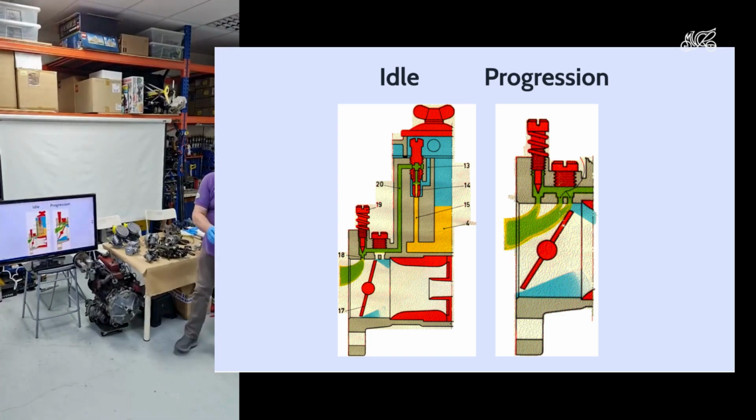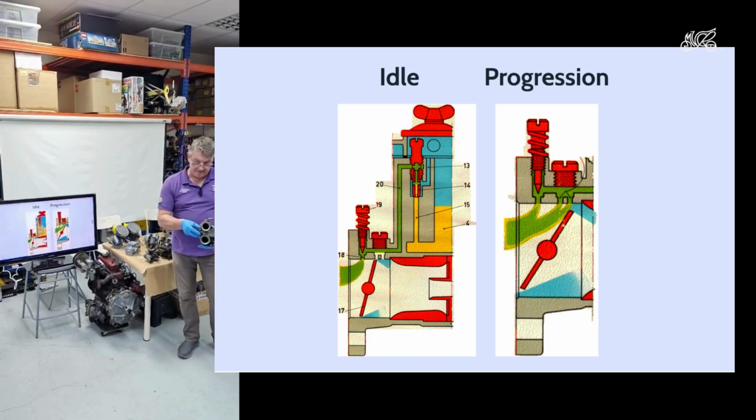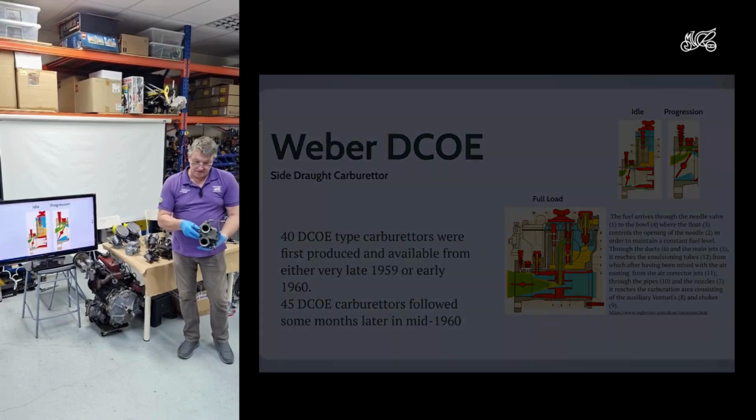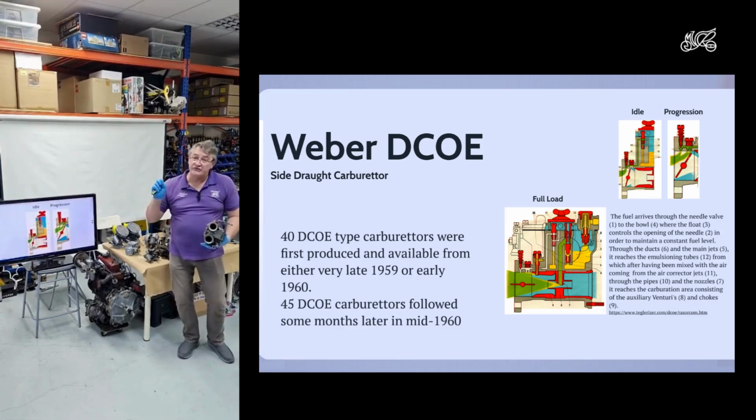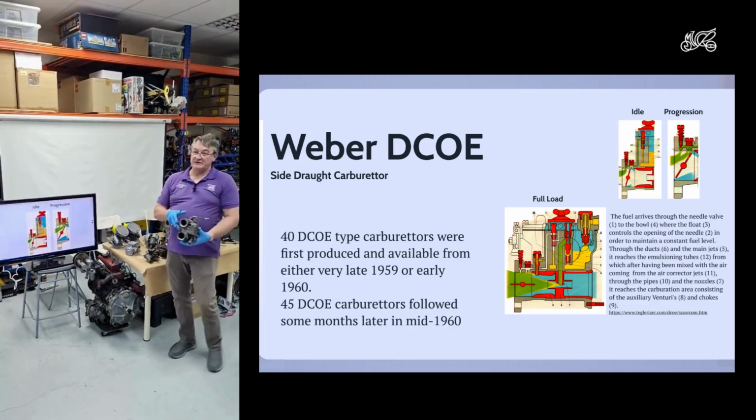I don't think these have them. So normally you've got another simple diaphragm pump. When you put your foot down, it presses a lever and it just squirts in a bit of extra fuel, gives you that richer mixture so the car accelerates cleanly.